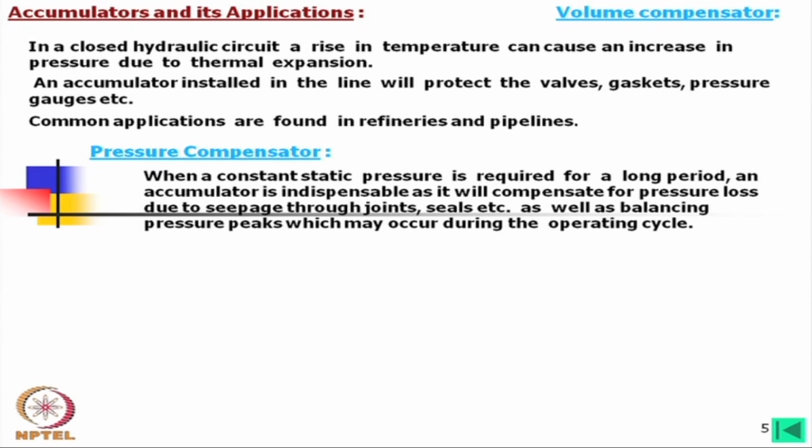So, this means that we have to first keep in mind that when the pump is running, excess oil is being accumulated in the accumulator. Now, if there is a loss, suppose the system is stalled, that means a weight is lifted and then it is stalled, then there will be leakage and so on. That leakage can be filled by the oil from such an accumulator.